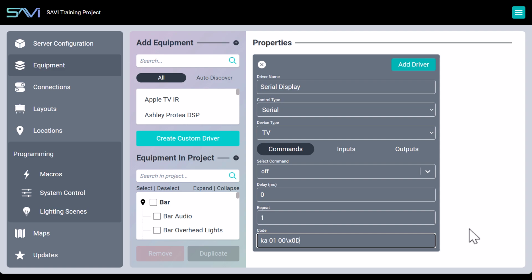Keep in mind, each device and family of devices are different. Some require carriage returns, some are case sensitive while others aren't, and some will ignore spacing, while others require spaces in specific locations. While the physical wiring or network issues may be contributing to errors, in most cases it's the codes for the commands that are often the root cause. You may need to try a variety of formats before the commands are executed properly.